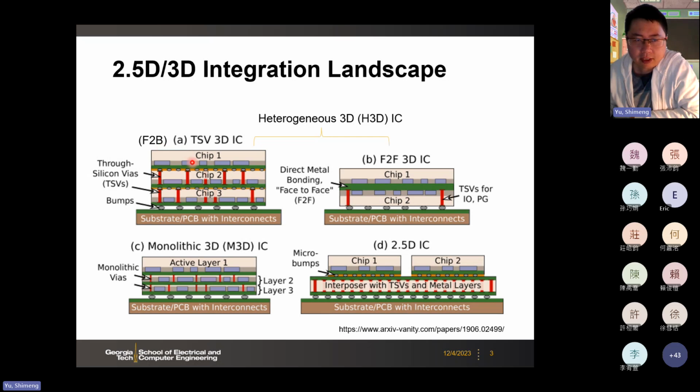So this is a face-to-back 3D IC stacking. This has actually been used commercially for some of the products today. For example, HBM, high bandwidth memory, is a good example for DRAM. For a GPU, the DRAM is typically HBM. HBM relies on 4 DRAM dies or 8. Even today, I think the most advanced HBM has 16 DRAM dies stacked in this way.